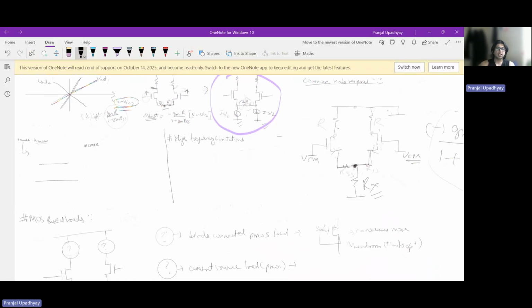And what I'm saying is that if you have along this line some common mode gain, and here you had your small signal fluctuation, and along this line you had some common mode gain, which again will be by the same amount, and again you had some small signal fluctuation. When you take the difference, the common mode signals basically cancel out, and in the end, by taking the difference, what you get is a normal differential signal output that you would expect.